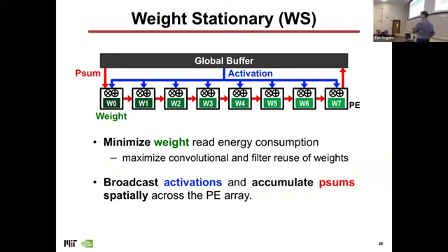If you're doing something like PIM acceleration, this is usually what you do. You do weight stationary. Okay, you program the weights. If you're doing a PIM, which is processing in memory, you don't really want to update it all that frequently. You want to use it for inference, meaning you don't update the weights. Then it makes a lot of sense to map the weights to the cells of the PIM array, and then that sort of represents the network.